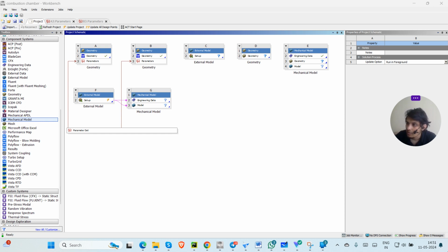Problem description: the case considered here is flow around a NACA 0012 airfoil at a 1.55 degree angle of attack and a free stream Mach number of 0.7. The airfoil drag and lift coefficients are the primary quantities. The pressure coefficient over the airfoil surface will be compared with experimental measurements.